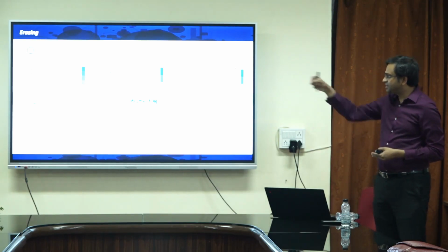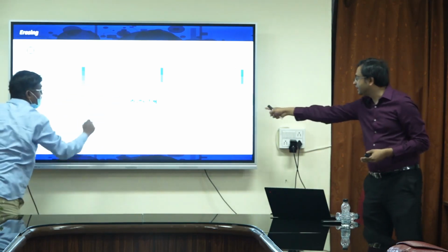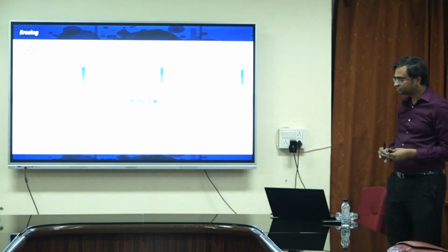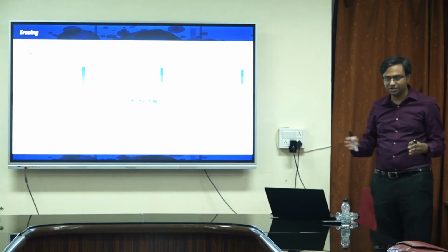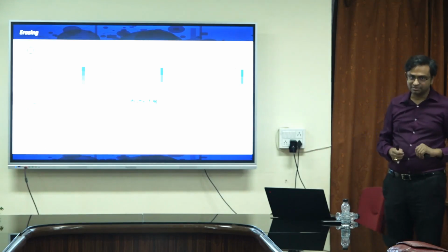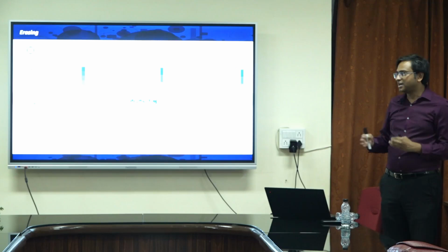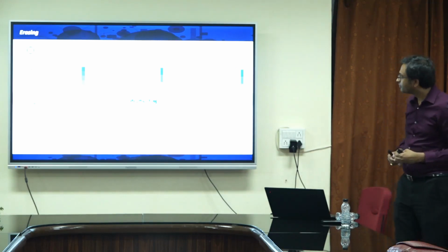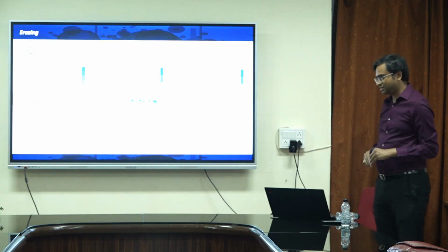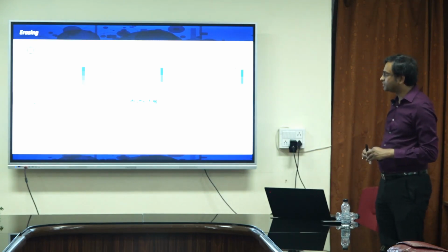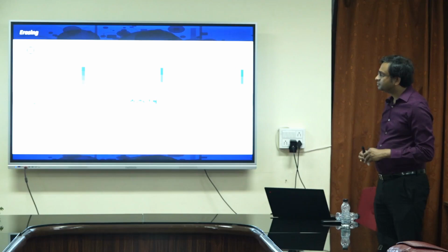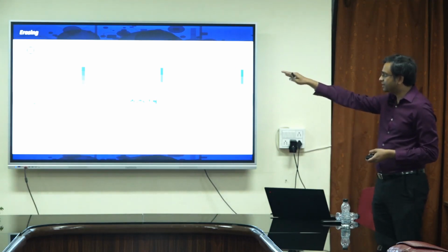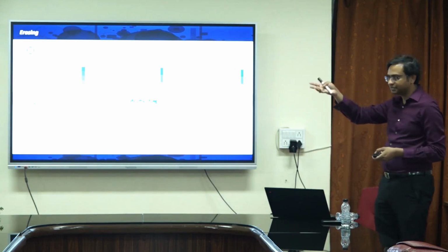For each of these it is done at 100 milliseconds, and here you can see also faster, down to almost 100 microseconds. So you can actually have a wide range of speeds for these devices based on how fast you want to learn or how fast you want to forget. GD is the conductance. GD is the value of the conductance. That's why we say high conductance state and low conductance state. So it goes from a high conductance state to a low conductance state, or vice versa.